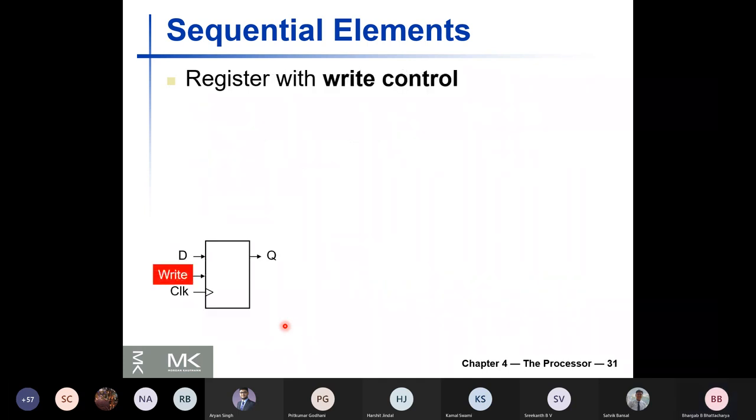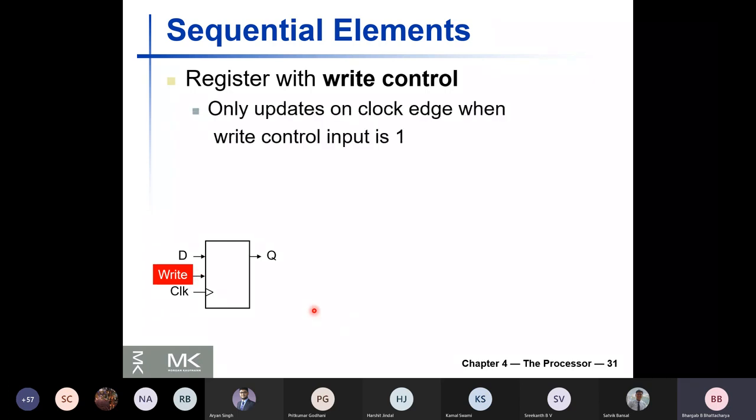Well, and we also, in the register file for each flip-flop, use an external control which is called the write, and this is needed so that you don't accidentally change the state of this flip-flop unless you really want to. In order to write, you need to feed the data here. You need to feed the clock. At the same time, this write signal should be enabled. Then only this flip-flop state will change. So this is done for extra safety, so that this output does not accidentally change with any other kind of stray signal. So it's called the register with the write control.